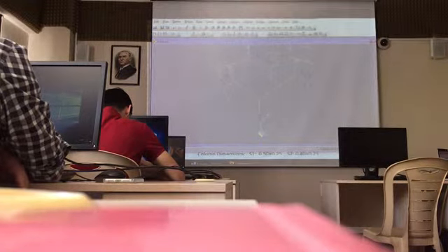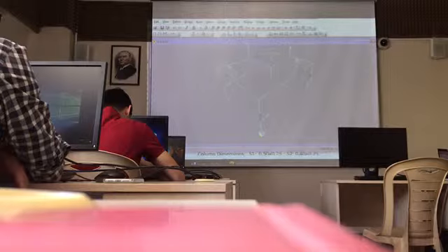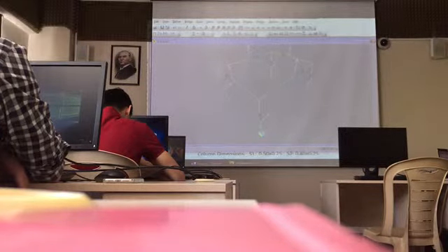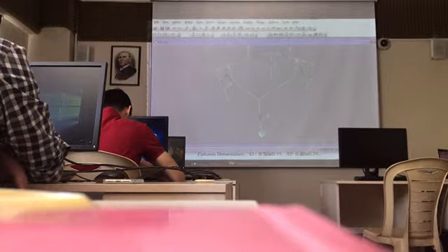Okay. Teacher, blue is Y, right? Blue is 3. Red is 1. You see red. Blue is 3. White is 2. For horizontal members, 2 is always upward in Z direction. For vertical members, 2 is parallel to X. Okay? Don't forget this. This is very important.